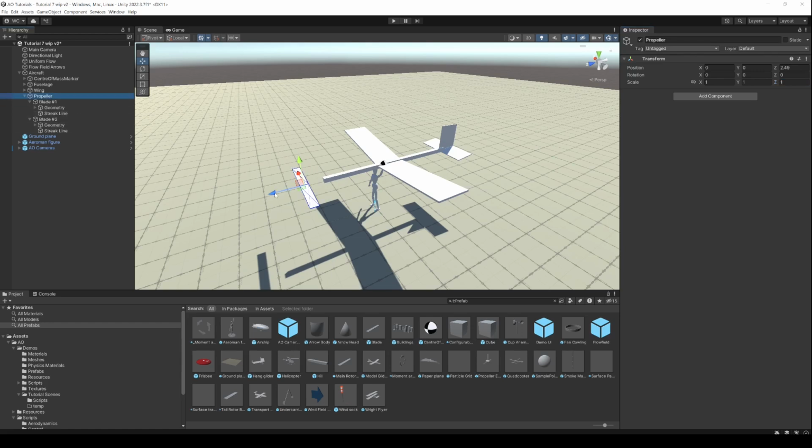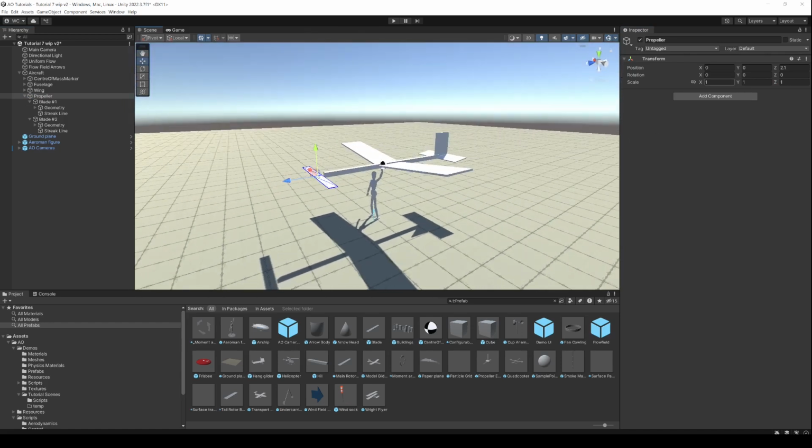Okay, and let's drag them back a little bit, put them on the front. So it's looking a little bit more like a propeller. But still, if we swizzled it around the Z-axis, all it would do is produce drag. So what we need to do is put some twist on it. We're going to do that in geometry, but we need to do it differently for each one. If we take blade number 1 and twist it about the X-axis by 60 degrees, and then go to blade number 2 and twist it by -60, we get some twist on there.